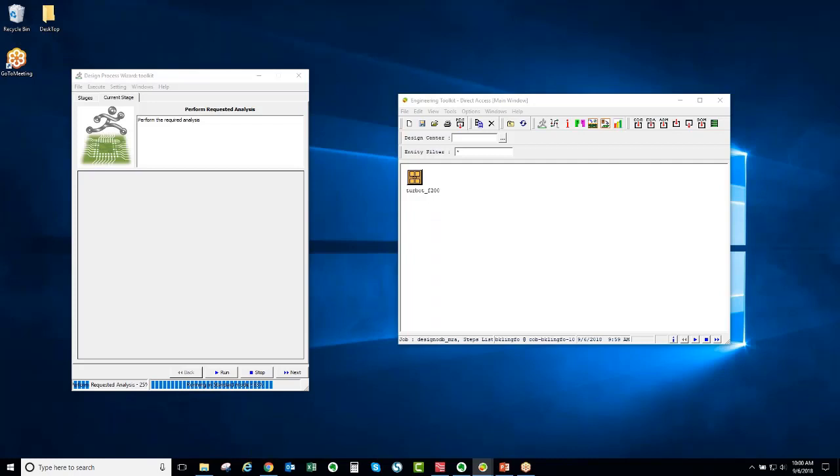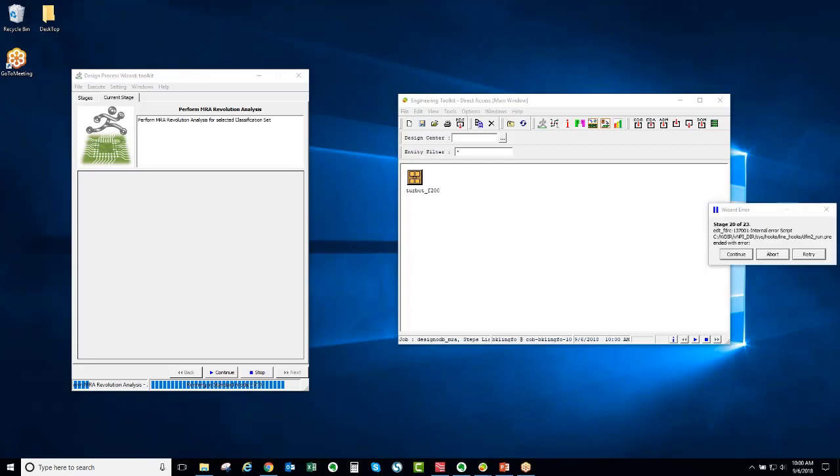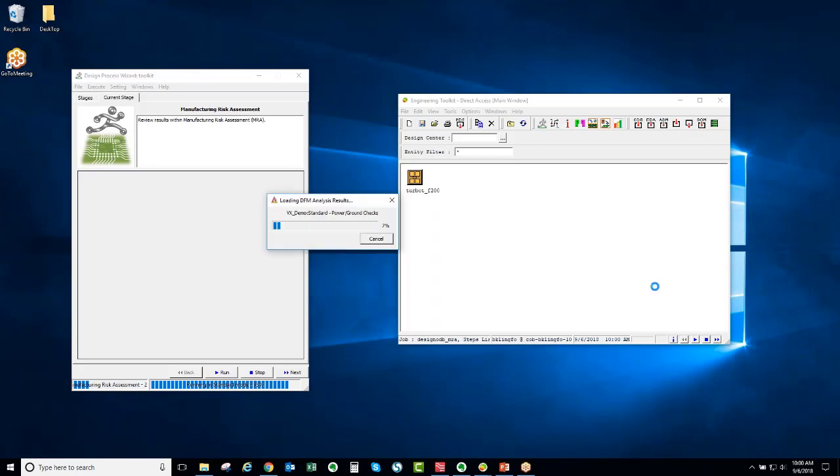Let's see, this would be a good time for me to go check to see if someone's asked any questions here. I've got a couple, looks like. How does one output ODB from Eagle? Personally, I've never used Eagle, so I don't know exactly what the process is for outputting ODB from that application. But like I said, Valor does allow you to import Gerber data as well, but it would be very advantageous if you could figure out how to output ODB++ data from Eagle.